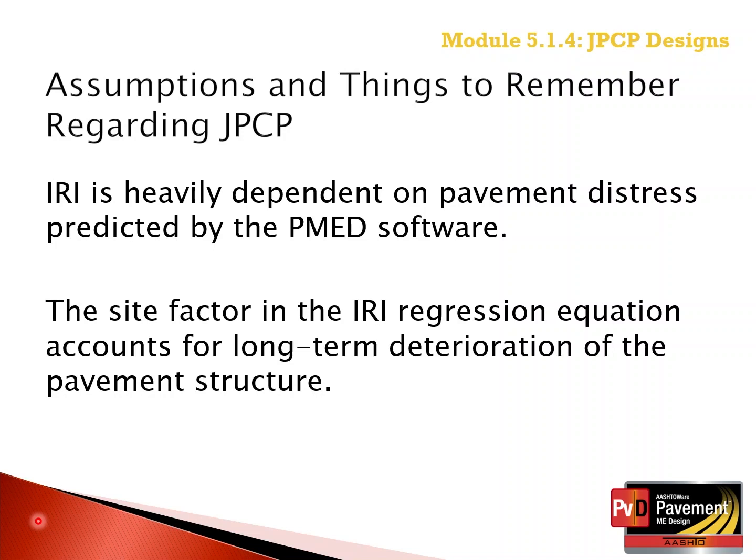Removing and replacing problem soils, for example, highly frost-susceptible soils or highly expansive soils, can reduce the impact of the site factor on the increase in IRI over time.